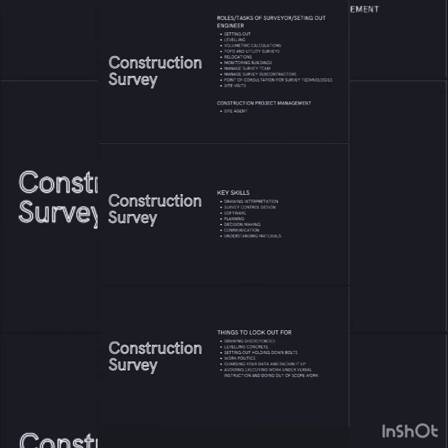In our opinion, road construction is quite easy. Building construction is something else. It's very difficult, especially that leveling part. The setting out, the holding-down bolts, setting out the columns, it's not as difficult as this. Because when you're setting out holding-down bolts and columns, as long as you get the column in the right position and you're using the bolts on a template, it's good. There aren't many parties involved in setting out those columns.